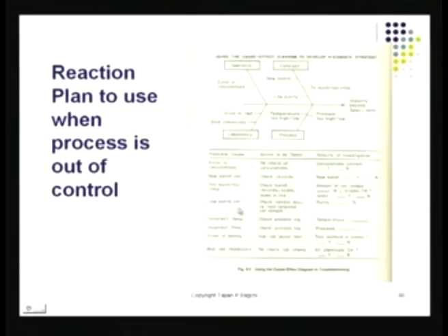You should not really do that. So you go over these things: low purity catalyst, that also could be a reason for this. Incorrect temperature, incorrect pressure, error in testing, or bad lab chemicals. So you're actually getting a bad test coming out of the laboratory.